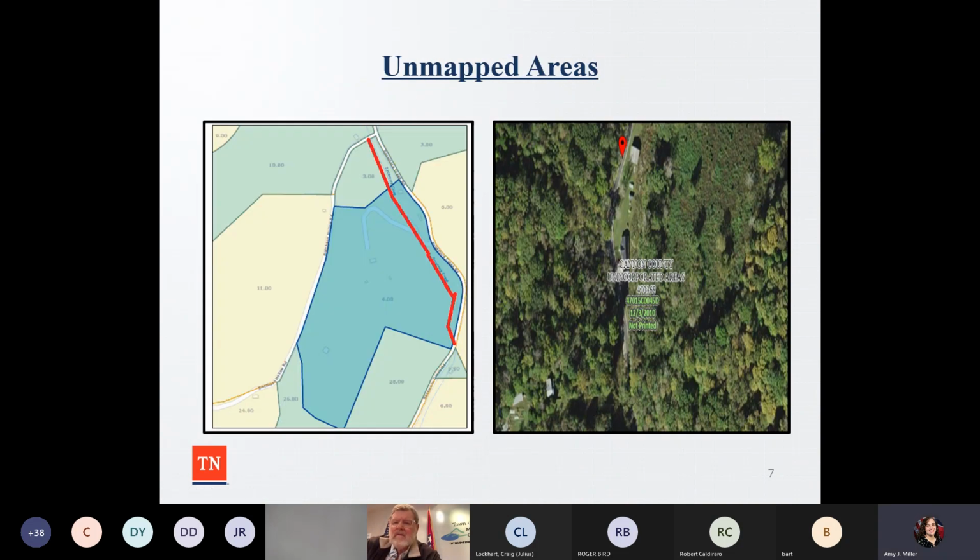We had a technical call a few weeks ago from Cannon County, where if you looked at the FEMA flood insurance rate map or the FEMA National Flood Hazard Layer, the pin shows that the property is outside the special flood hazard area. So you think, okay, it's in zone X, I have no worries. But if you look here on the left-hand side, when we looked at the Tennessee property viewer, there is an unmapped stream. With this unmapped stream, the property owner has to make sure that the development encroaching on it is moved, or else they do an engineering analysis.